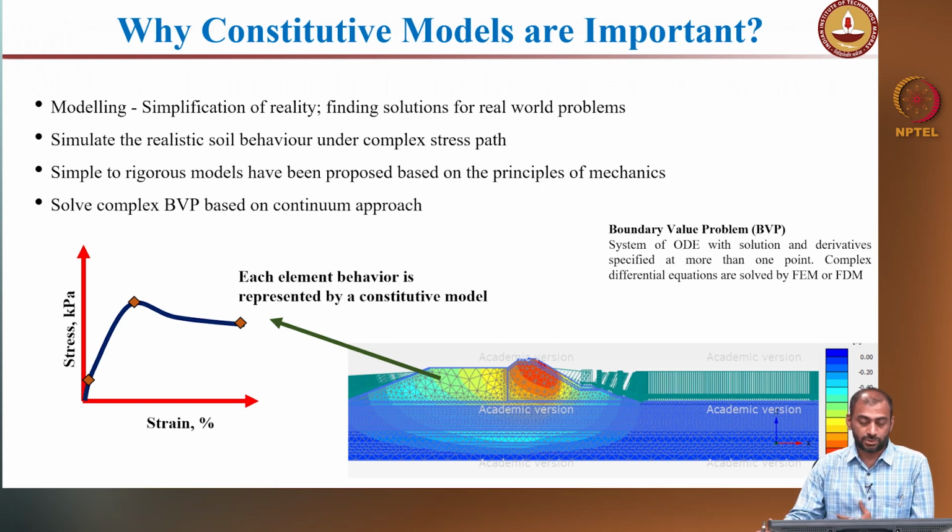The models can simulate a complex stress path, and these rigorous models are proposed based on the principles of mechanics. Once these continuum based constitutive models are developed, they will be used in tandem with the numerical methods which have been discussed in this course, using finite element methods or finite difference methods. You can use these constitutive models and solve some complex boundary value problems. So, this gives an idea why the material models or the behavioral models are really important, right.